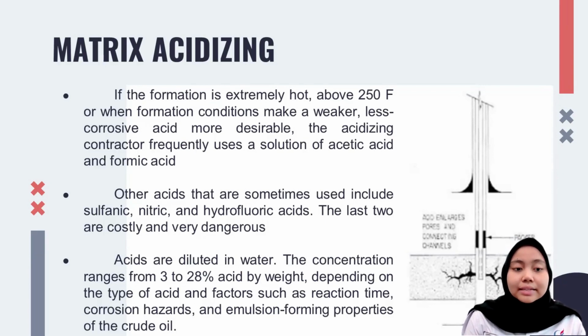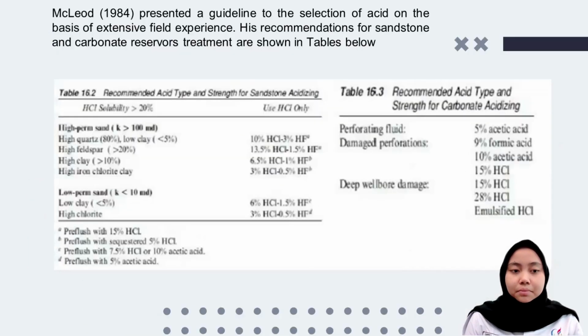Third, acids are diluted in water. The concentration ranges from 3 to 28% acid by weight, depending on the type of acid and factors such as reaction time, corrosion hazards, and emulsion forming properties of the crude oil.